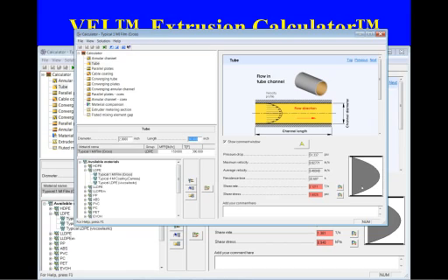Well, the software here will show me the velocity profile, the pressure drop through that adapter, 51 psi, average and maximum velocity, residence time. But it'll also highlight two numbers, the shear rate and the shear stress. And when I put my mouse in that box, it'll pop up a little window saying the shear stress should not be less than 4.35 psi.